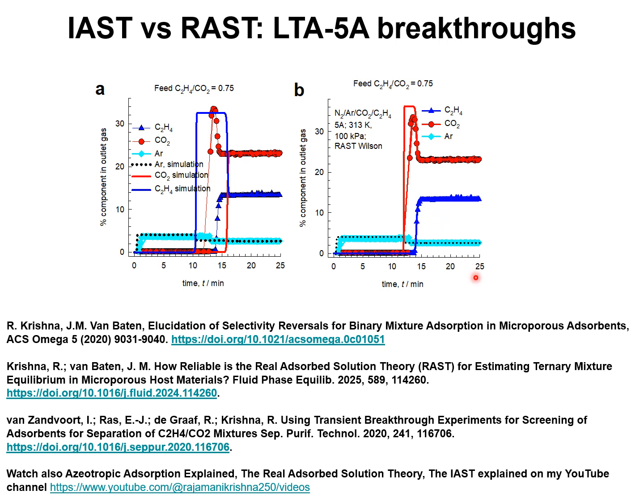2 important conclusions that emerge from these presentations are the following. For recovery of C2H4 from the products of the OCM reactor, we need adsorbents that are selective to ethene, and the crucial selectivity is of ethene with respect to CO2. Activated carbon is a candidate adsorbent.